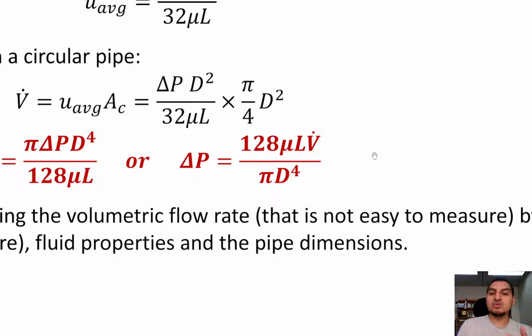So we have two contradicting factors when we choose the diameter. First, we can think of the pressure drop. So we say we will pick a very big diameter, but the pipes with very big diameter will be very expensive, so we cannot increase the diameter a lot. At the same time, it's more economical to decrease the diameter.